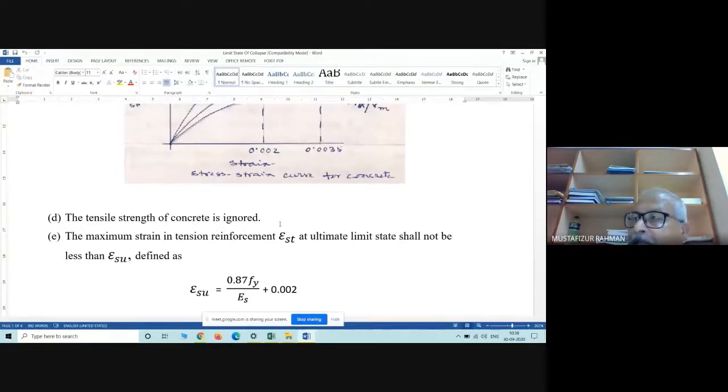It is sagging, and near the support it remains constant. Because of that, with respect to the neutral point, the bottom part will be subjected to extension and the upper part to contraction. The bottom part subjected to tension will be subjected to tensile stress.